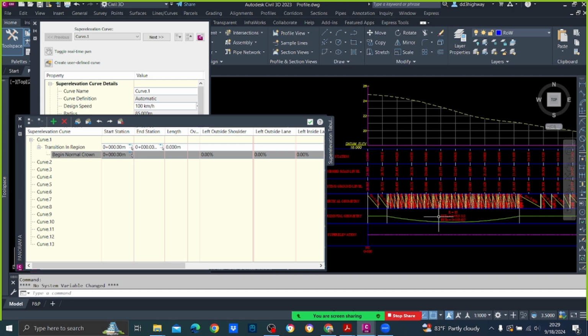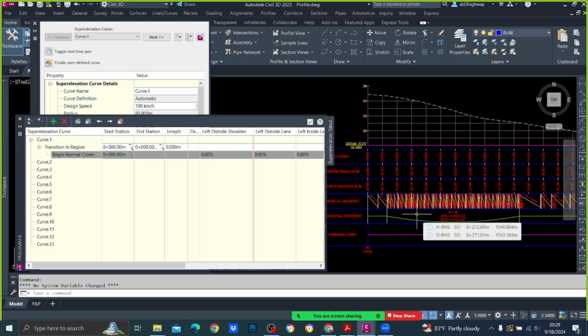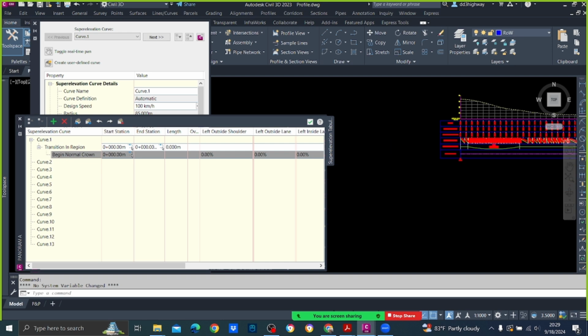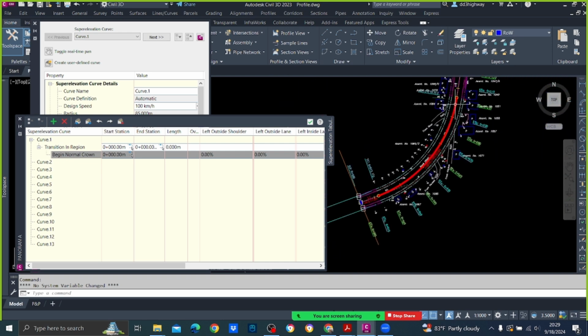So here this is turning this side, in an anticlockwise direction. That means the RHS side should be elevated. Understood? Now just create in your mind a road. There is a curve and it is turning in here. Can you see? It is turning this way, so this side should be super elevated.